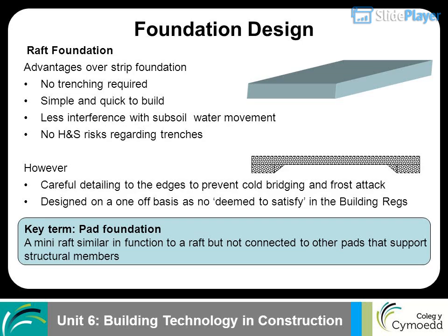Foundation design: raft foundation advantages over strip foundation. No trenching required. Simple and quick to build. Less interference with subsoil water movement. No H&S risks regarding trenches. However, careful detailing is needed at the edges to prevent cold bridging and frost attack. Designed on a one-off basis as there is no deemed to satisfy in the building regs.